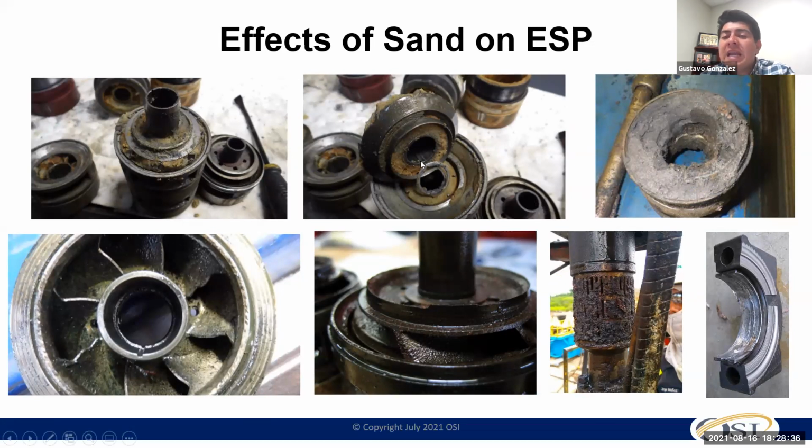When I'm lifting that frac sand, based on the number of shutdowns I get on my wells, or the inflow and the drawdown, you're going to see that you slowly start plugging your stages to the point that the ratio of sand is more than the ratio of liquid. You can see that it's plugging your system 100%, and the amount of erosion it can cause to your pump is going to be high.